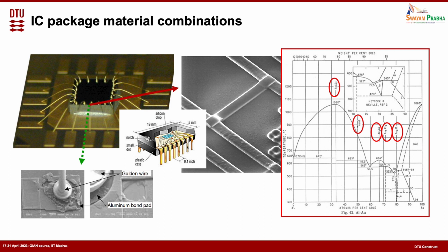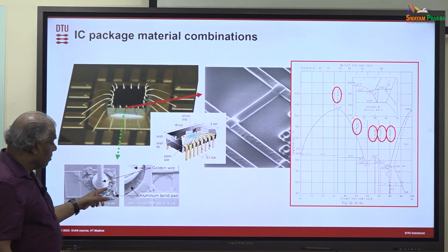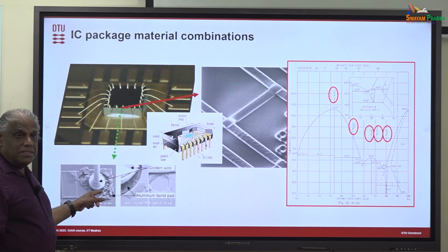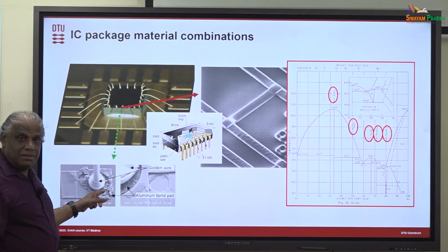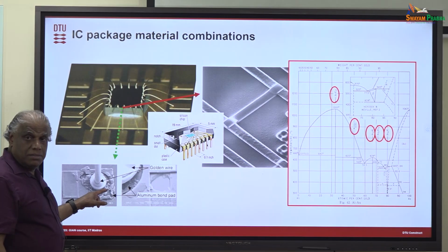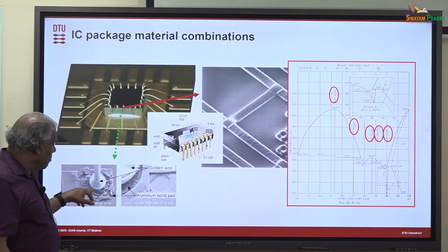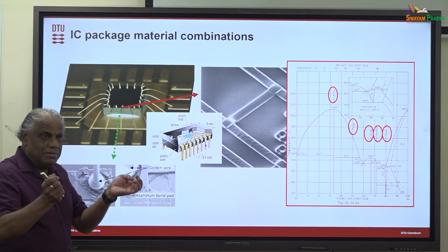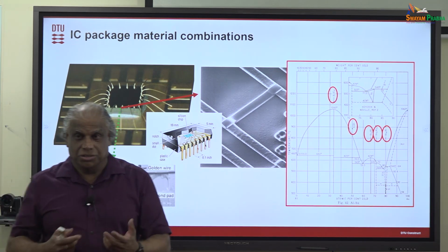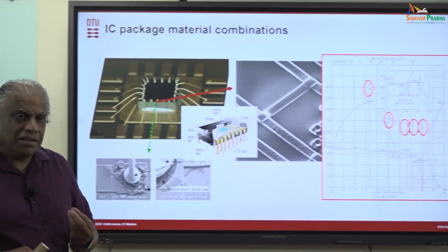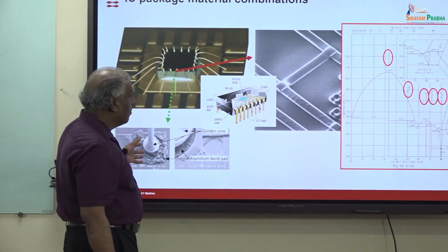During and after the welding process, when the IC is in use, the IC temperature can go up to probably 80 degrees centigrade from self-heating. Slowly, these intermetallic particles will grow at the interface. What's the problem? These intermetallic particles are brittle compared to this bond. So when the intermetallic forms, only a little bit of corrosion turns it into a fatigue failure. So very little corrosion is enough to get a fatigue failure and debonding.